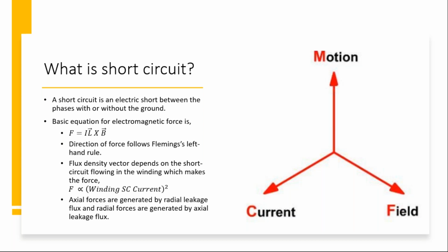But there is a time lag between the fault and the circuit breaker operation. During that moment, any connected equipment will see a huge amount of current, based on the rating and the design of the winding and its damping effect. Those currents can be more or less than the normal inrush current, but it can vary from design to design.